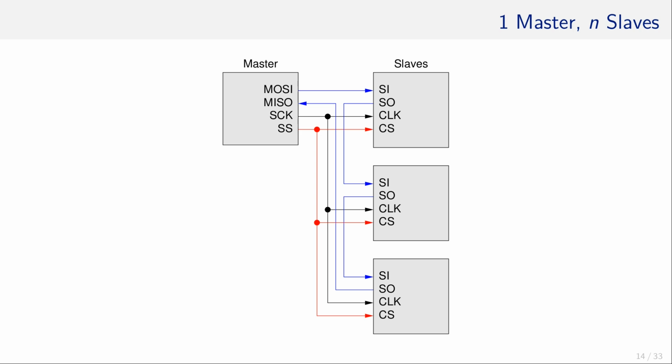For instance, the third slave carries the data from the second slave now. How does it know the source of that data? It could be an attempt of the master to communicate to the third slave, or it could be a data packet from one of the slaves located in front of it in the chain. So daisy chaining SPI slaves comes at the cost of a more complex data management.